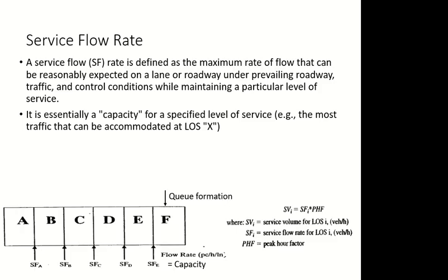So yeah, the equation which you see here is the relationship between volume and flow rate. Volume equals flow rate into peak hour factor. So if you are taking maximum flow rate, you will get maximum volume. If you are taking service flow rate for A, you will get service volume for A.